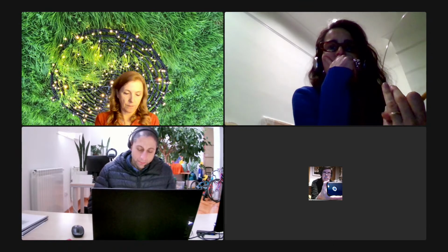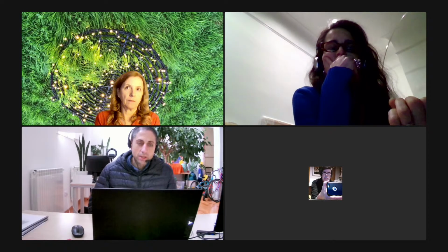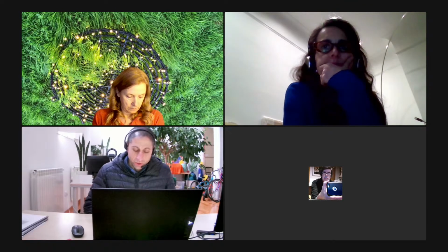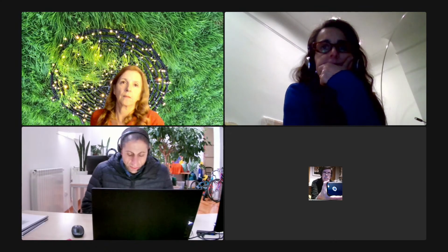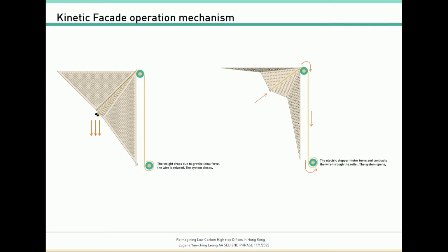And then as for the environmental objectives of reducing the embodied carbon, I think maybe some clear disclaimers of the assumptions and the quotes that you are taking should also be added to the analysis and to the comparative charts when you compare the alternatives. For instance, in your kinetic facade, I'm not sure what the materials are. According to the images, it seems it's metallic, and so that would be an additional carbon footprint for the building compared to other materials that are not so environmentally intensive. If that's made of bamboo as the structure, well, that would be even better.